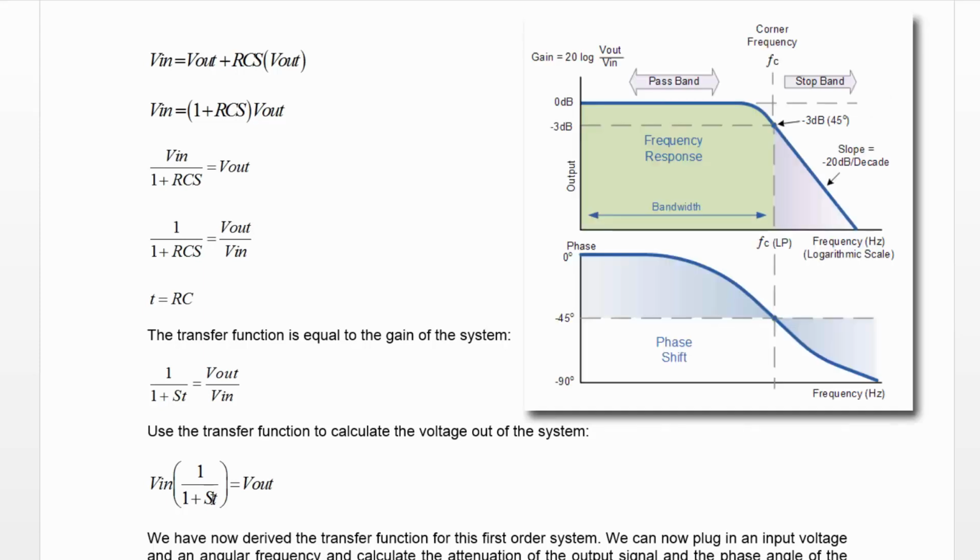And this is what we call the cutoff frequency. When that frequency times the time constant equals 1, it's what we call the cutoff frequency. And at resonance, 70.7% is the effective bandwidth. In other words, that is the effective bandwidth that you can use. So we're using 70.7%, and we call this minus 3 dB.